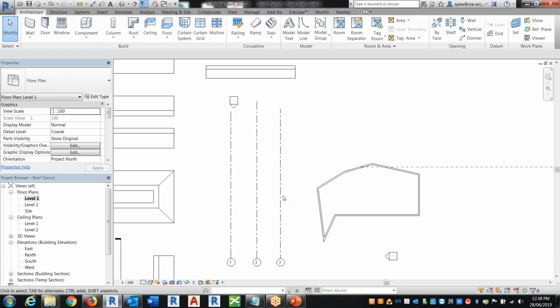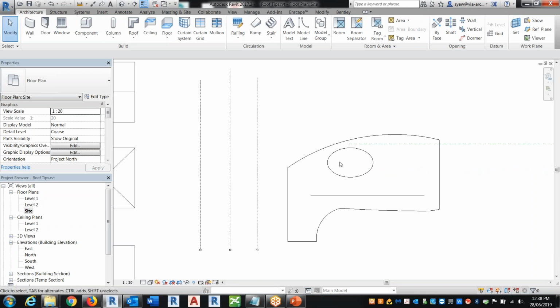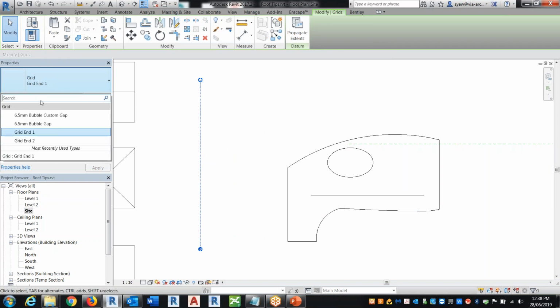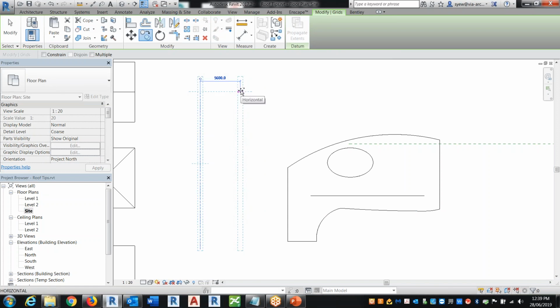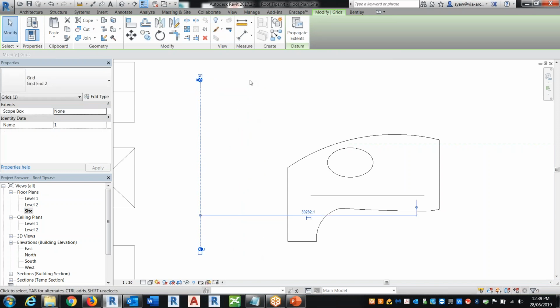I know that this can get very annoying. People say, I like to create one. If you can create one, that's fine. Make sure that everybody follows it. The good practice I always do, if you're doing a grid, so I'm just going to get rid of it. Let's assume that I want a grid 2. Always array it or copy it. Don't draw one grid, then draw another grid.